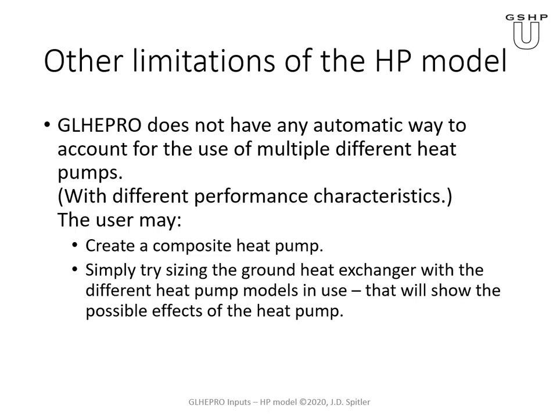So in that case, the user could create some kind of composite heat pump, right? Try to combine the performance of the different heat pumps. Or you could just try sizing the ground heat exchanger with the different heat pump models in use, and that would give you some idea of how much effect the heat pump has on the design. I think in many cases it will be relatively small. It's not zero, but